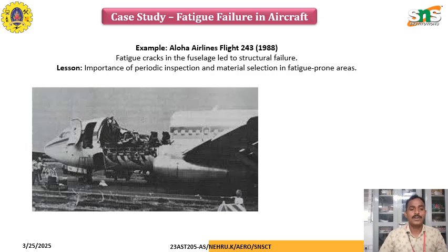Let us go through a small case study example. The example of Aloha Airlines Flight 243 in 1988: the failure was due to fatigue loading in the aircraft structure. Fatigue cracks in the fuselage led to structural failure. The lesson we can understand is the importance of production inspection and metal selection, and that fatigue-prone areas need to be given attention.